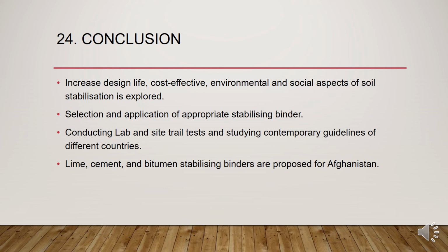While selecting stabilizing binders, the application and appropriate stabilizing binders should be considered, and conducting lab and site trial tests and studies of contemporary international guidelines and literature of different countries are very important, and more investigation and more research are required. Lime, cement, and bitumen stabilizations are proposed for Afghanistan, which are easily available in the market, cost effective, and can be easily implemented at the site.